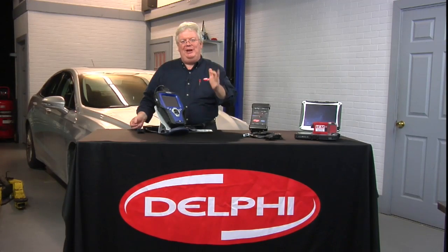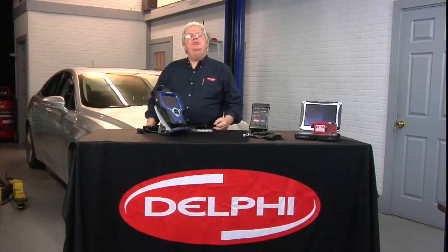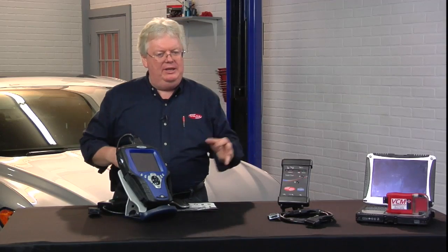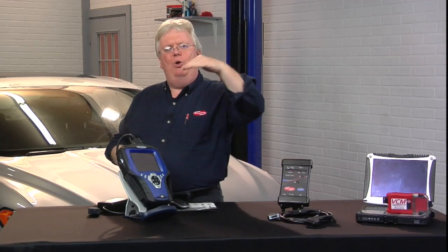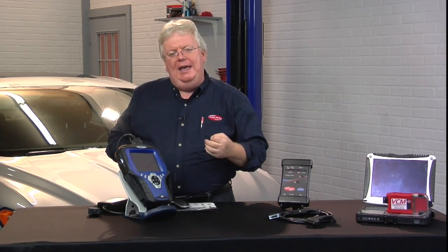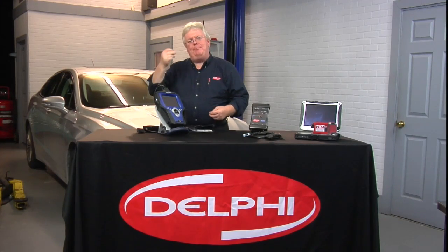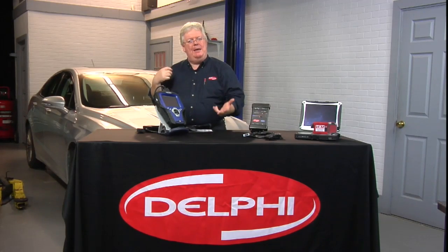The question is, mode 6 data updated continuously while driving? Well, technically, mode 6 is a study, snapshots in history of the non-continuous monitor. So a monitor that only updates once or twice per drive cycle. So you get in the car, you do a 40-degree sweep up in temperature, you do your speed up, your idles, the whole thing to get you the drive cycle, hopefully. And those batch of monitors all run, but they just run at that point in time. So technically, the answer would be false in that regard. They're not constantly updating evap, boom, boom, boom, every mile or two down the road, for example.